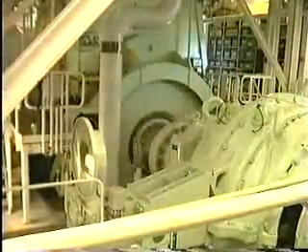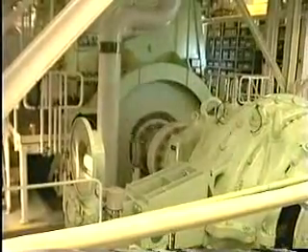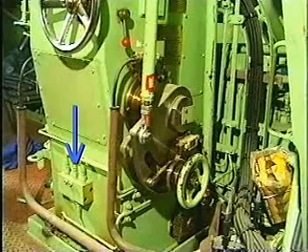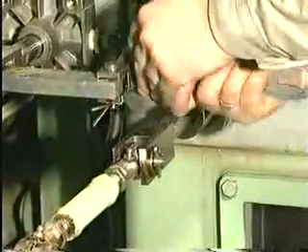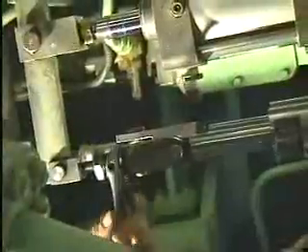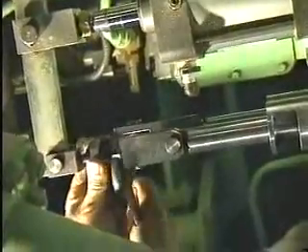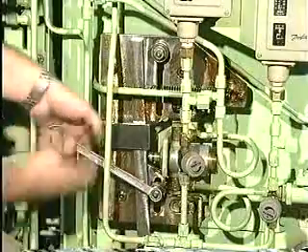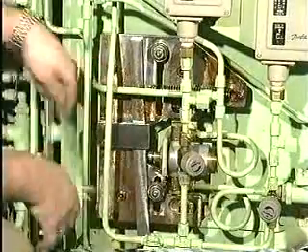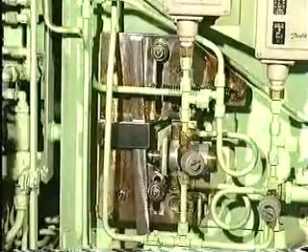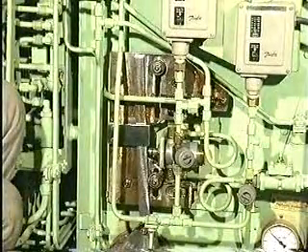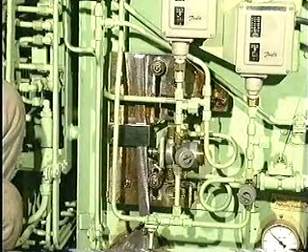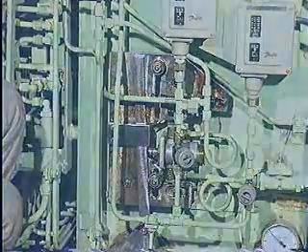Start the engine and run it up to a load corresponding to the brake point. Make sure that the control air pressure is able to pass the changeover valve. Fine adjust the links so that the maximum combustion pressures, corrected to ISO ambient conditions, are uniform and have the required value. Load the engine until it corresponds to 100% MCR, and fine adjust the lowermost pivoting point so that the maximum combustion pressures, corrected to ISO ambient conditions, are uniform and have the required values.